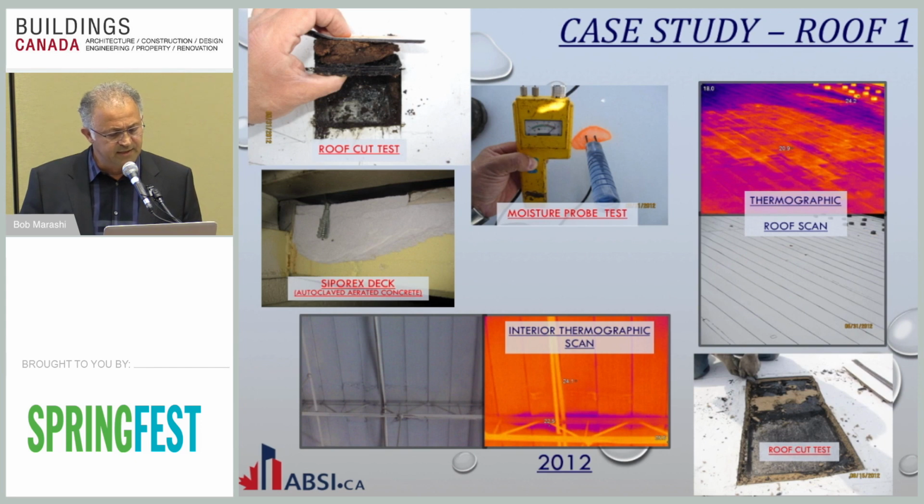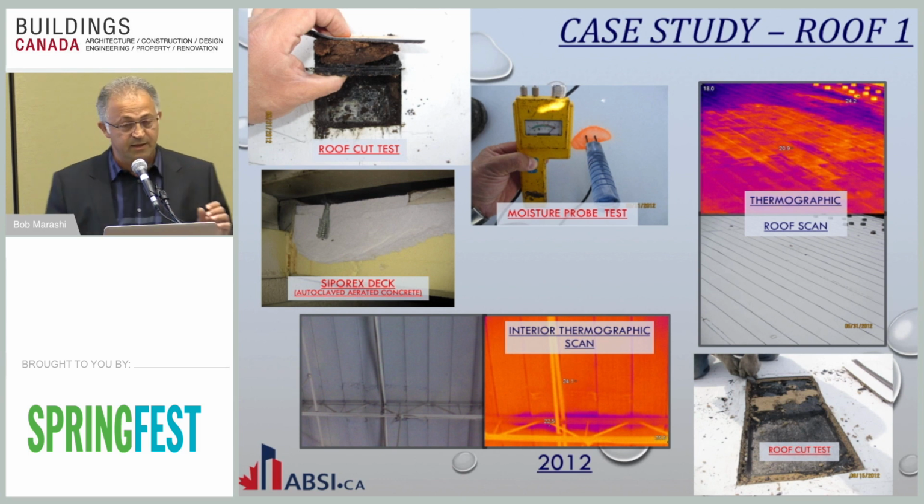We did some cut testing. We did infrared thermography on the surface of the roof. We also did infrared thermography inside the building for the underside of the deck. The decking that was at the building at the time was Suprex panels, which is aerated concrete deck.